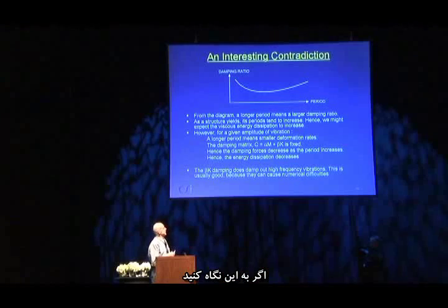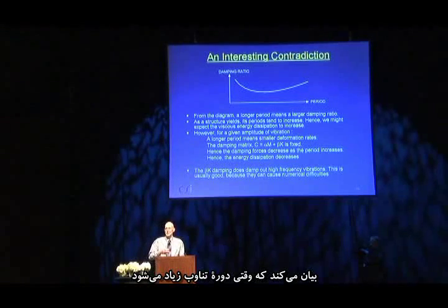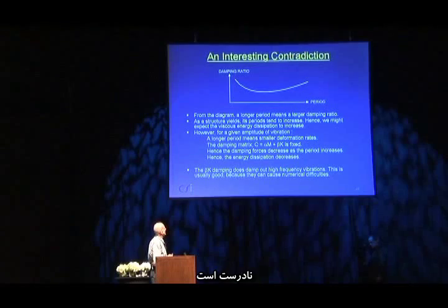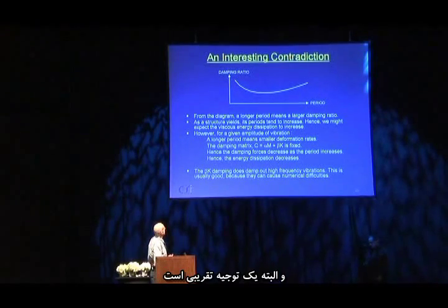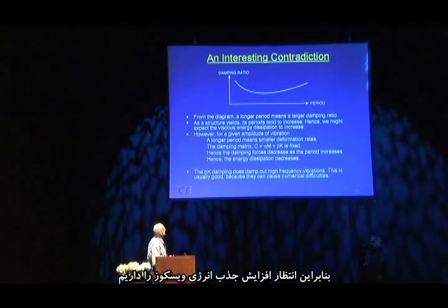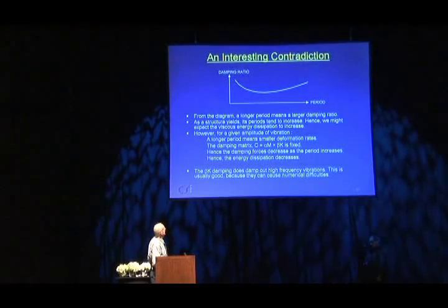This would suggest that as the periods increase, the amount of Rayleigh damping should get larger. However, that's not correct. I used to think that too, but the reasoning is false. As a structure yields and periods increase, we might expect the viscous energy dissipation to increase. But let's look at this.